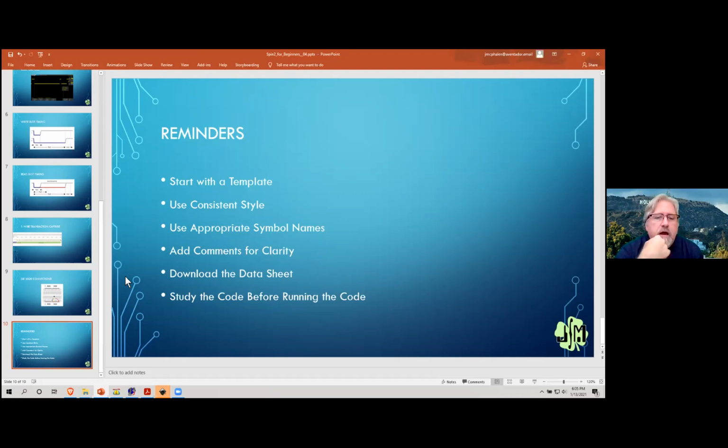For example, again, working in entertainment, I do a lot of stuff with DMX. I found it was just cleaner because DMX does this kind of non-standard thing with a pulse before the packet of data that goes out. Instead of playing games with the smart pin, it was just easier to do the UART code in software, because I'd done it before in the P1 and it's actually much easier in the P2. So we can talk about those kinds of things and doing non-standard things.